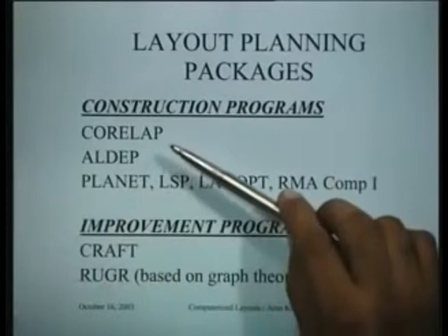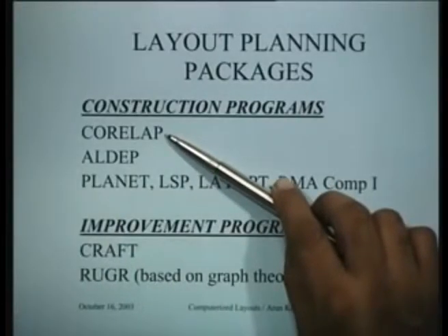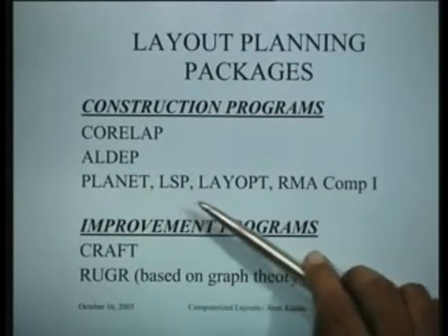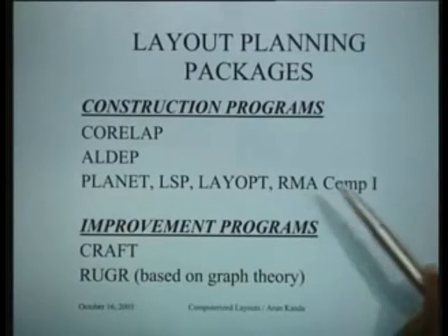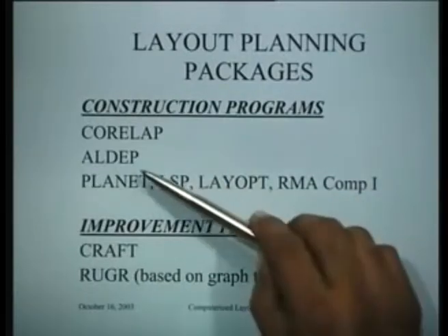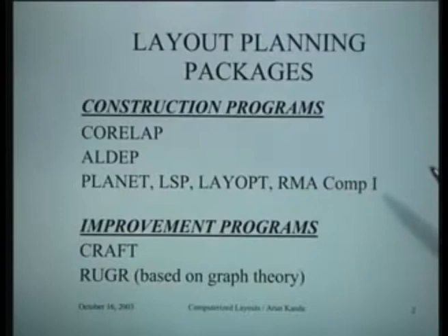By utilizing the information that is available about the layout, you can generate a layout from scratch. And the important programs in this category are CoreLab, ALDEP, Planet, LSP, Layopt, RMA, Comp1. These are all commercial names, and we will look at one particular type of construction program in detail, that is ALDEP, which was one of the early programs that came on the scene, and it summarizes the mechanism by which the layout plans can be generated.